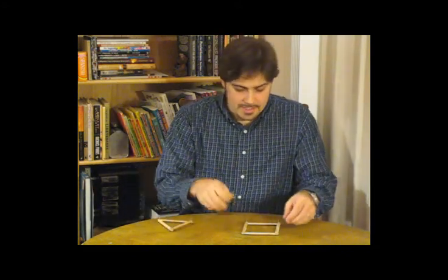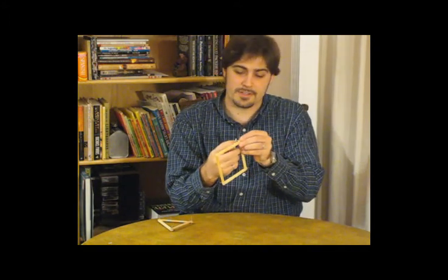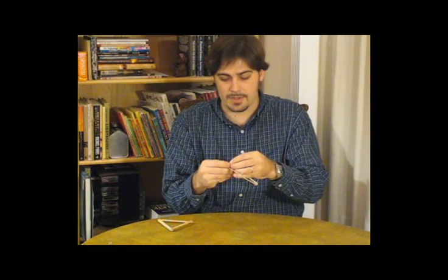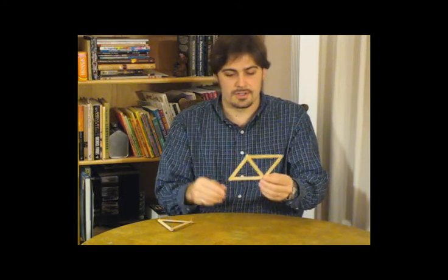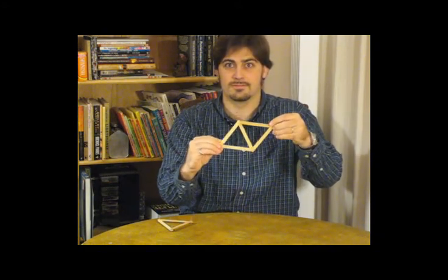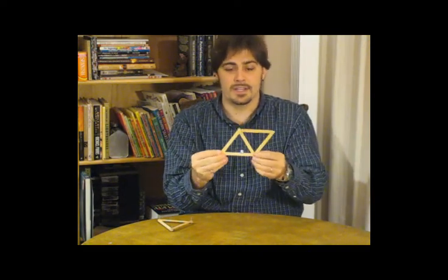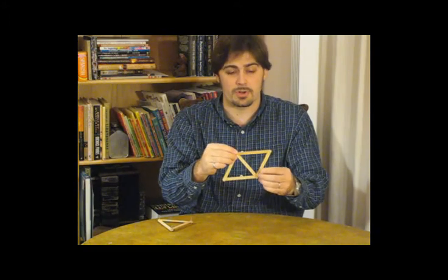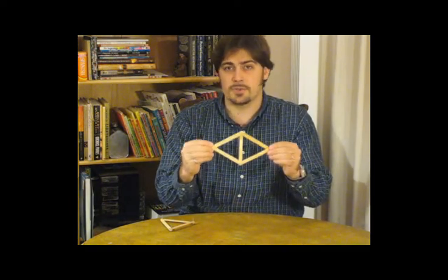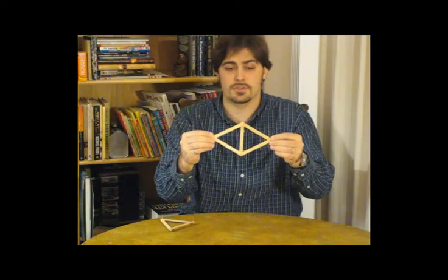All right, so I guess the next question is, is there something we can do about this quadrilateral? Well, there is. We can stick a member across the diagonal of the quadrilateral, and you'll see that if you do that, it changes this structure into two different triangles. And you'll see that now that structure only has a unique shape. So it's made entirely of triangles. It's lost that mobility, which in this case is something we were trying to do in order to make that structure more rigid. All right. Now this by itself is a truss. It is a structure that derives its strength from having its members arranged in triangles.